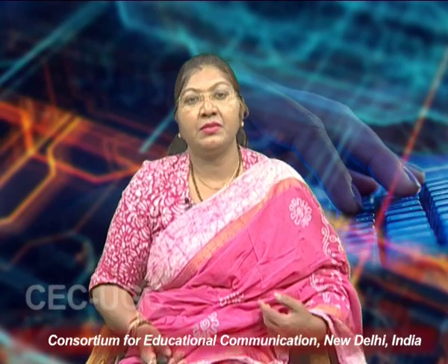The configuration called the rigid flex PCB is often a way to take advantage of each format at the same time, or to connect multiple rigid PCBs with the flex circuit instead of wires and the wire harness. The advantages of the flexible PCB also make them a good match for designs that use high density interconnection, which allows engineers to create the rigid flex PCB with more compact circuitry, thinner layers and micro wires, all while having a flexible portion in the PCB design.